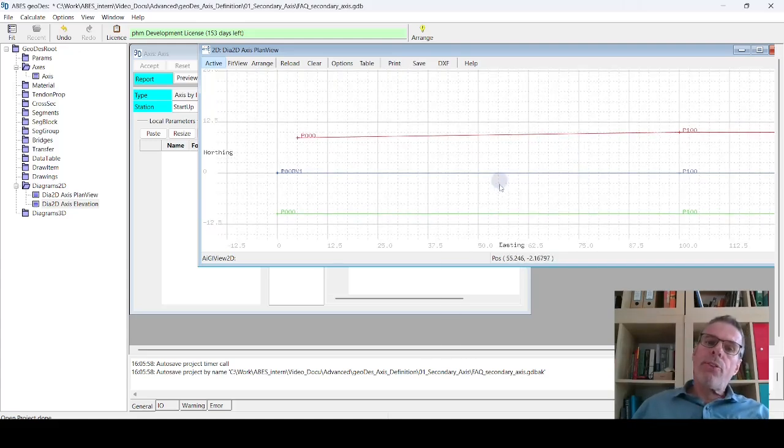What's also noteworthy here is the fact that we've moved this point to the 30-degree skew, and the conjugate calculation, the conjugate chainage or conjugate station, is from this point at the skew angle to this point, and this is station 0 on our secondary axis.